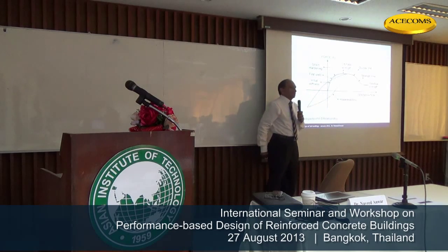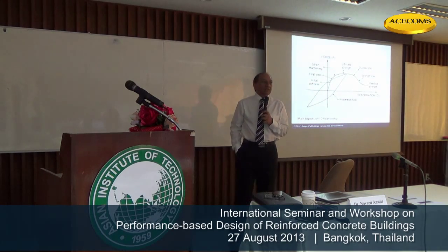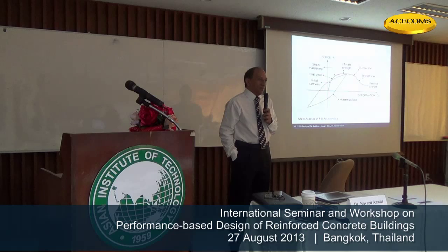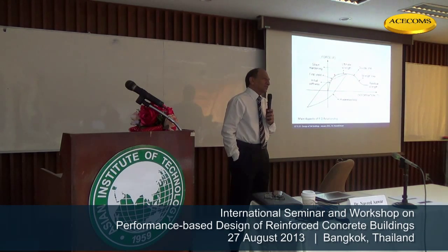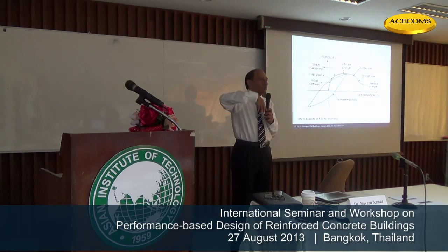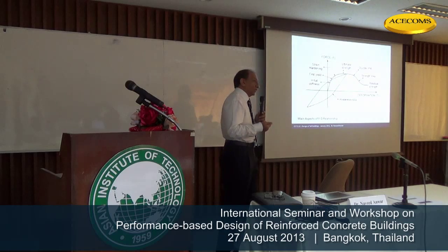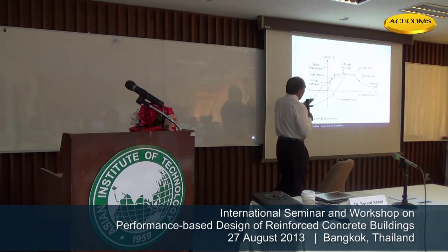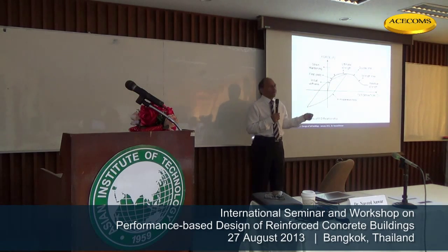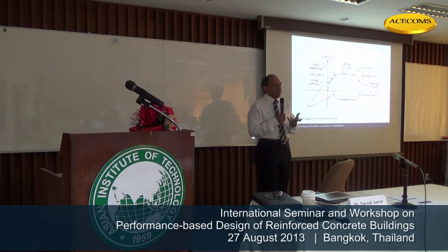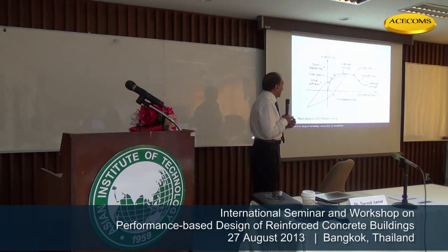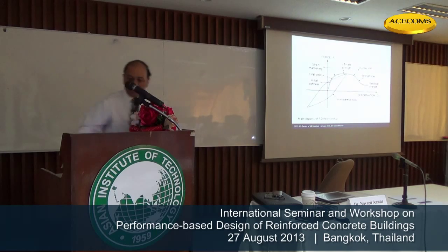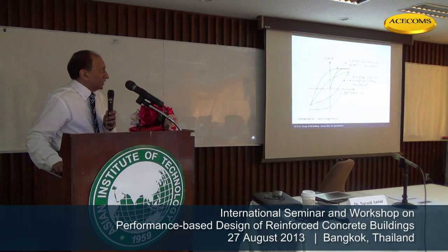This hysteretic behavior is the key. We can use it to our advantage, or it can be a disadvantage. How can it be an advantage? It can be energy dissipation, because we can use this to dissipate energy, absorb energy, seismic energy. Or it can be a disadvantage. It can lead to degradation and different collapse of the member. So we use this information in the right way.